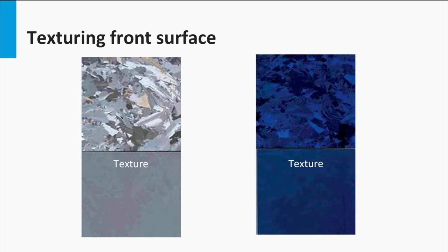Here we see a flat multicrystalline silicon wafer with and without silicon nitride. Under these wafers we see two wafers with and without silicon nitride layers as well. The only difference is that the two wafers at the bottom have textured surfaces. The wafers are placed in the same illumination conditions as the flat wafers. By eye you can already see that these surfaces are darker and therefore reflect less light.